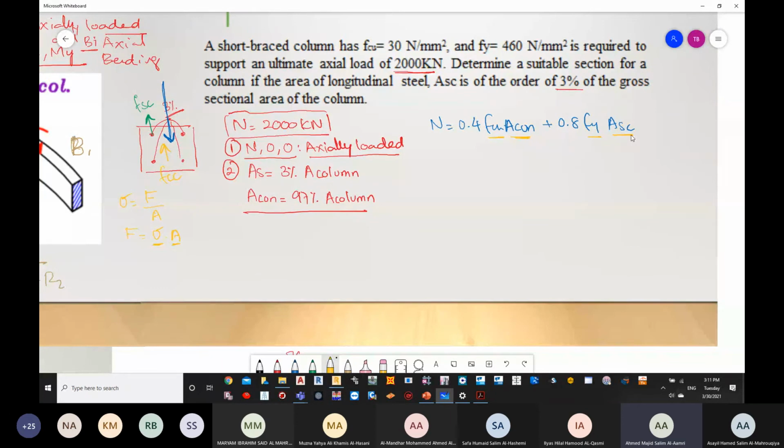If you remember, the maximum stress in case of concrete is 0.67 fcu divided by gamma m. The same thing, maximum stress for steel is fy divided by gamma m, 1.05. So different values are there, and if you go for the derivation, this is the equation that comes up. If there is time in the next class, then I'll show you how this has been derived.